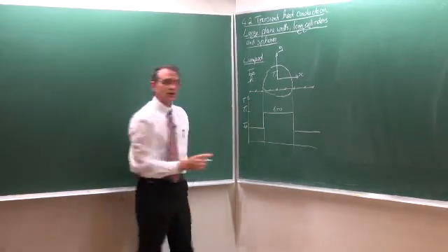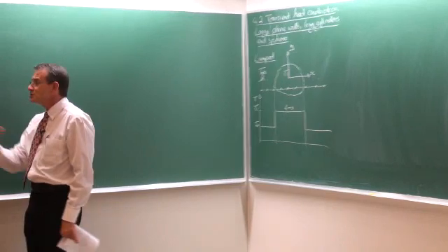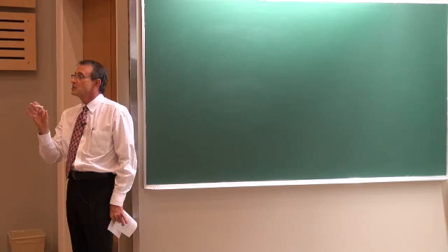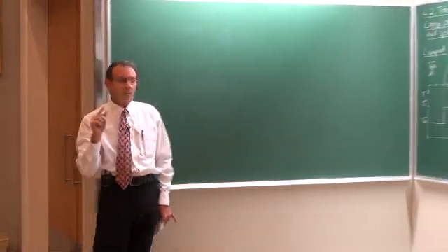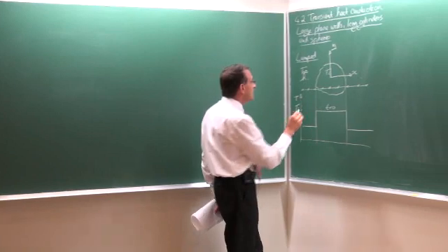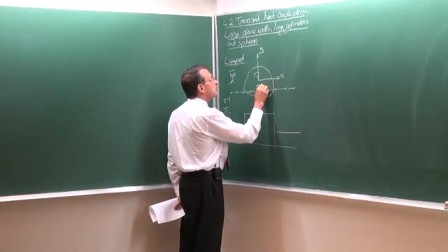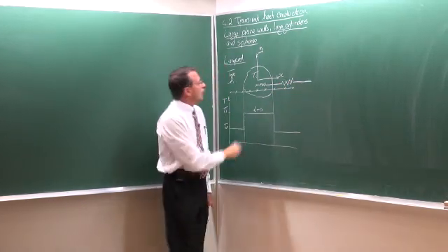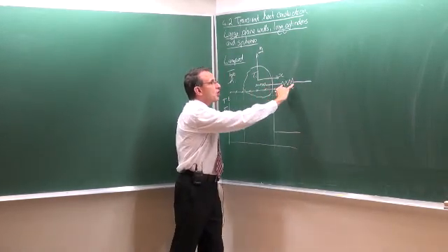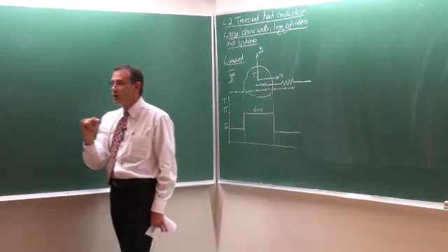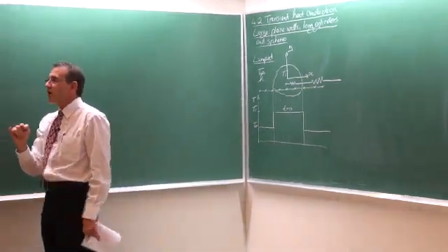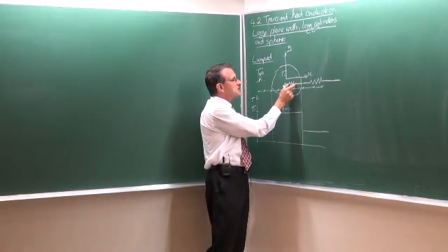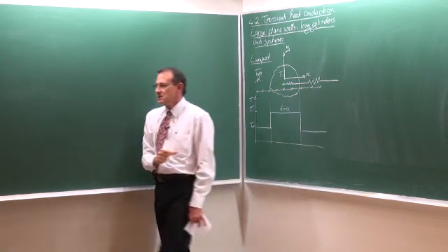All of the points in the body give us the same value, which is not realistic. We know that is not correct. So that is what the lumped system is all about. It's a very important assumption in the sense that we say the resistance of conduction divided by the resistance of convection, the Biot number, must be smaller than 0.1. So it would give us a good answer if this resistance is 10 times smaller than that resistance.